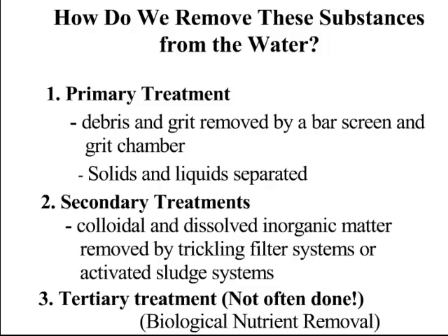Now at the end of that process, it goes into another holding tank, and that holding tank, it just sits there again, and the solids drop out of it. So we're converting the sewage into microbes, and those microbes are large enough that they can drop out of the water and be collected as sludge. So what we're left with is liquid that then would be called secondary effluent. So this is the second stage. It's the water that's left at the end of that. That's secondary effluent. And all of the sewage has been taken out of it, but what's left in it is a bunch of plant food and a bunch of pathogens.